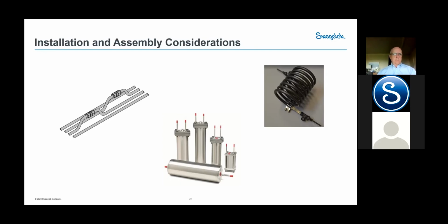Tube connectors and welding take up the expansion and contraction without an issue. Threaded connections are not very tolerant of expansion and contraction, and it always causes issues. So those are the methods. Does that help?